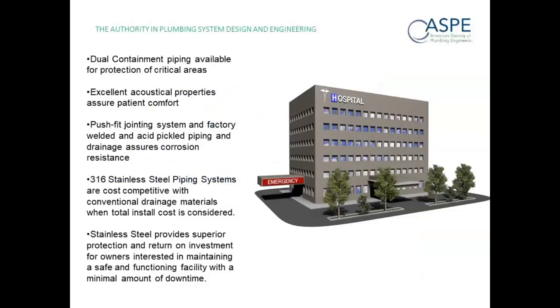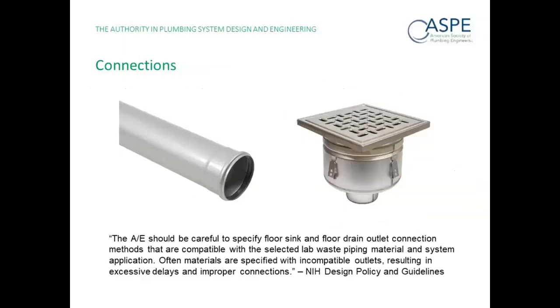Absolutely. So we'll talk a little bit about the different features and benefits of stainless steel in healthcare and critical areas, in particular push fit systems and their cost competitiveness, how their joint systems work, ROI, and acoustical considerations. So let's advance right away. One of the critical areas that's been pointed out in the NIH design policy and guidelines, and I see there are a few healthcare designers on here, is that they are very specific that the architect or engineer should specify drain and piping connections that are compatible with your piping system, because that often becomes a leak point. So just a reminder on that.